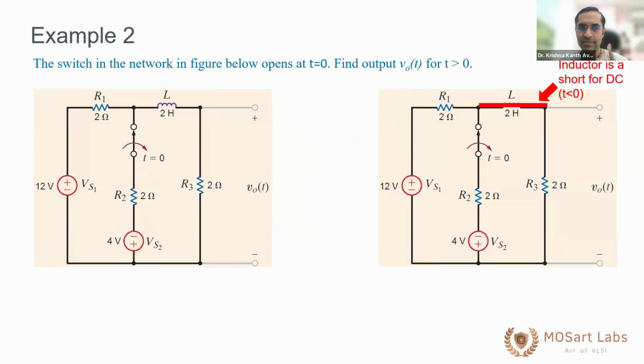So what did we use here? The superposition principle to find the initial condition. Then we checked the initial voltage by assuming the inductor to be a short, and the final voltage also assuming the inductor to be a short. We calculate the time constant and then we found the answer. So I didn't do any differential equation here. No differential equations. Clear? Of course, that doesn't mean you don't need to know it. You can of course solve it that way.